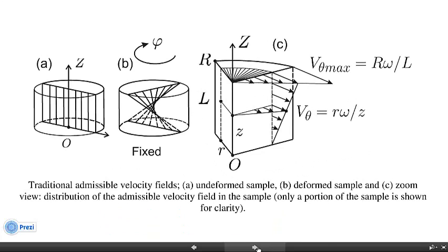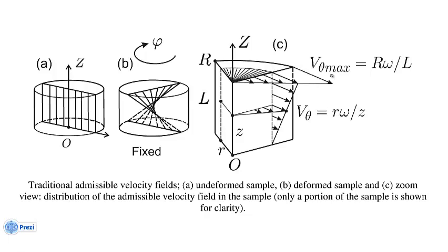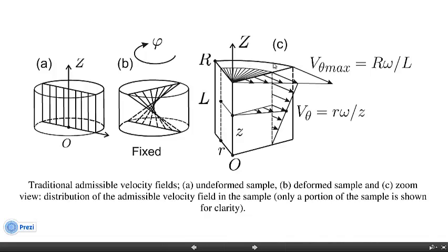analytical technique is about. The immediate conclusion from these assumptions is that the material velocity field can be described by one single velocity component, the tangential velocity, because the process is a zero shape change process. Height doesn't change, the diameter doesn't change, and the only deformation is due to shearing stress from tangential velocity. That velocity is zero at the center. It linearly increases to its maximum at the periphery, and again there's a linear distribution from top to the bottom. That maximum velocity vanishes to zero here in a linear sense.